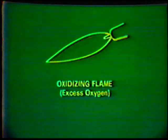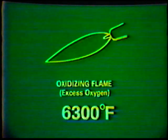The third type is the oxidizing flame, which has an excessive amount of oxygen in the mixture. Its temperature is approximately 6,300 degrees Fahrenheit. This flame is used for welding brass and bronze and for brazing galvanized steel and cast iron. It is easily identified by its short inner cone and a harsh hissing sound.